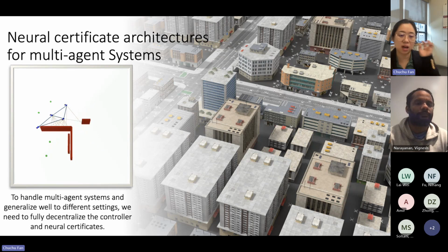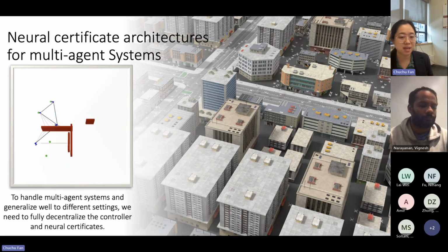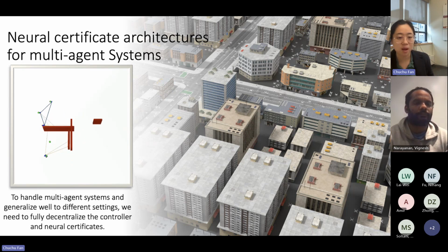At the same time, you can see the thin lines here. Those are the LiDAR. The LiDAR here is primarily for understanding what's around in the whole world that cannot communicate with you. For example, the red things are obstacles, and these obstacles could move around, and our agent has no prior knowledge of where the obstacles are, how big they are, or anything about obstacle movement. Now, our requirement is that the agent will reach the destination on time without colliding with the obstacles and without bumping into each other. So I would say a fully decentralized controller in this setting is the promising way to